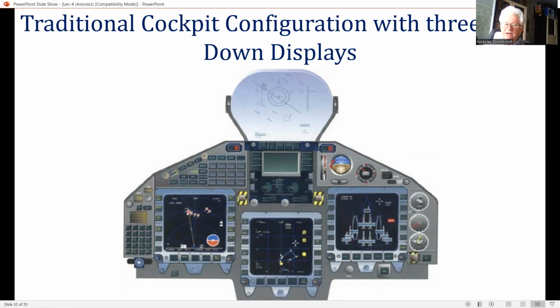the display. So-called tactile surfaces are being introduced using such techniques as infrared beams across the surface of the display, or even surface acoustic waves, where the pressure applied can also be measured to give X, Y, and Z coordinates. Typical advanced military cockpits are configured with 4 head-down displays.